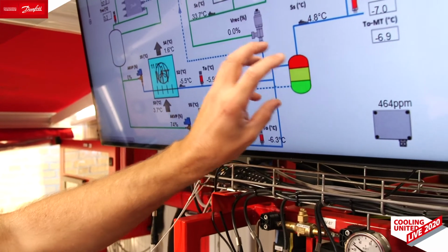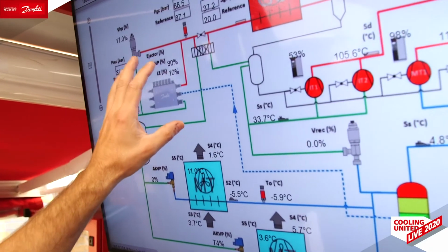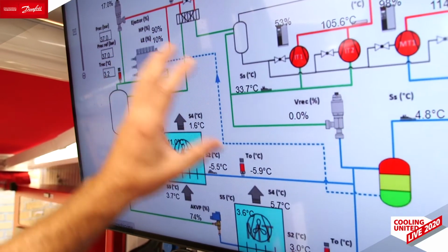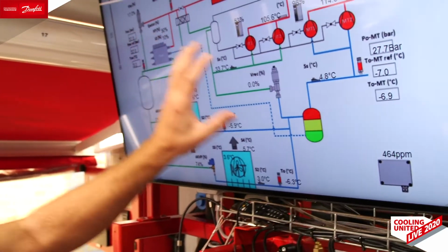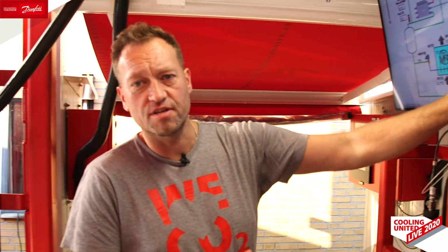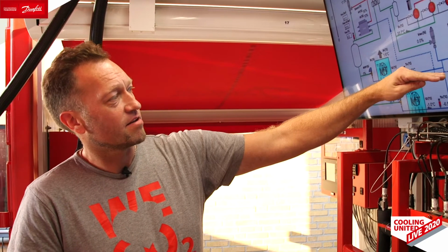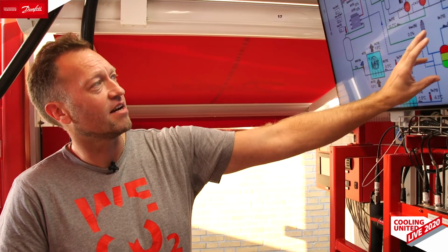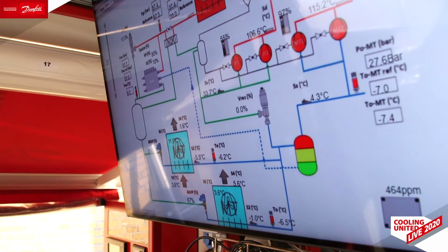And this very little amount of liquid combined with the efficiency of the ejector means that we are able to remove all the liquid from the accumulator, and that you don't have to dimension the site with a parallel pump or similar to move liquid. There might be some cases where you need to leave the CALM mode to prevent that an error in the system starts to build up refrigerant in the accumulator, and therefore risking to damage the compressors. So we have some safety precautions in the system.